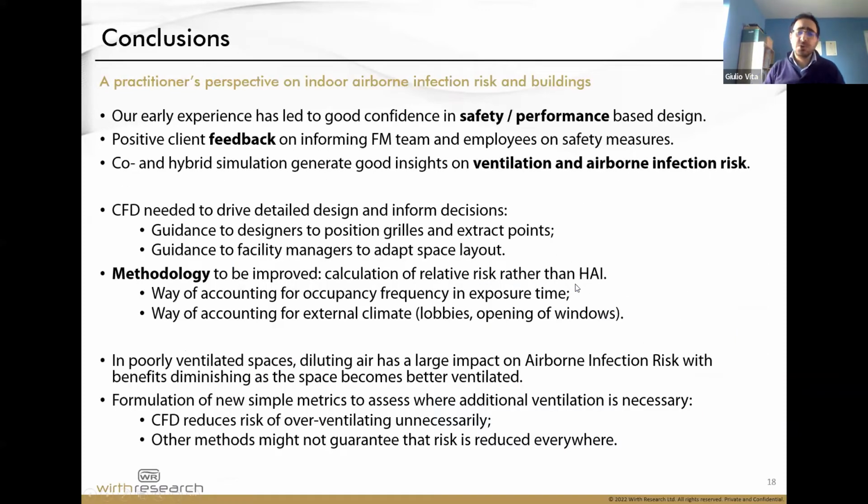If we want to conclude, we can say that the experience so far has been positive with modeling airborne infection risk, meaning that the clients normally are very responsive and give positive feedback. We can also say that there are still lots of uses for CFD, can provide guidance to designers, to architects, to facility managers. The methodology needs to be improved. So for instance, we should start talking about relative risk rather than modeling a physical parameter.